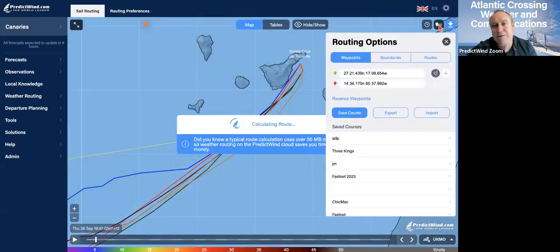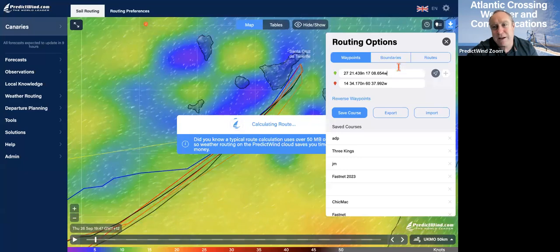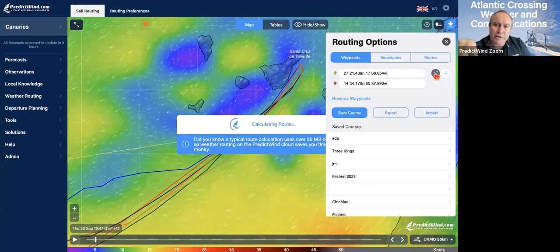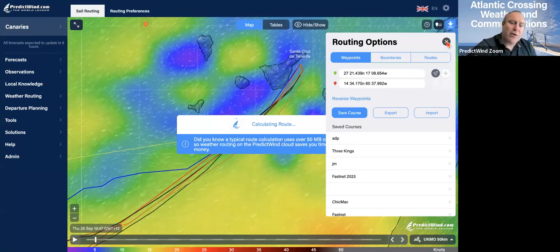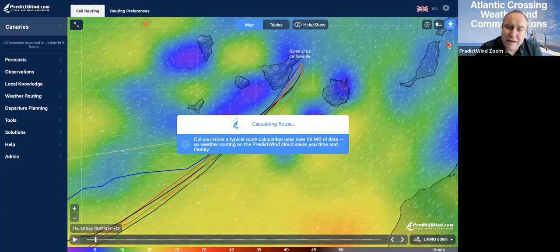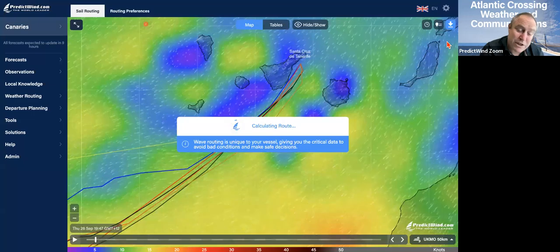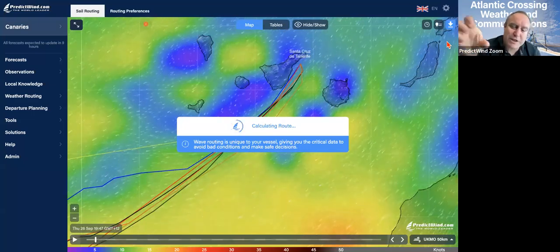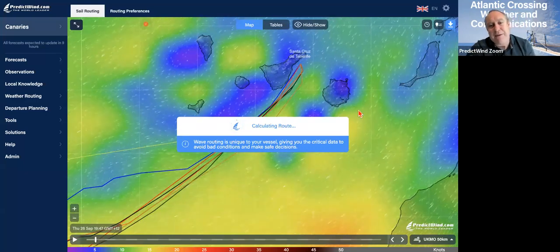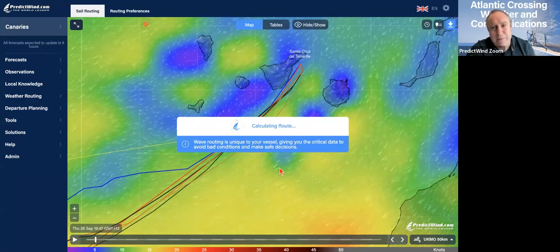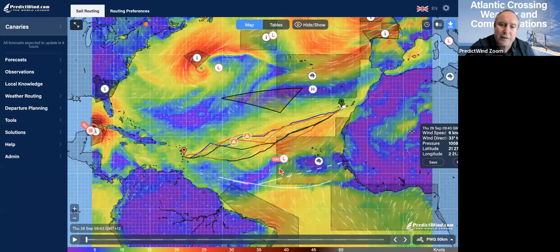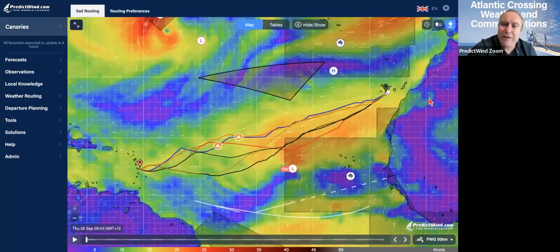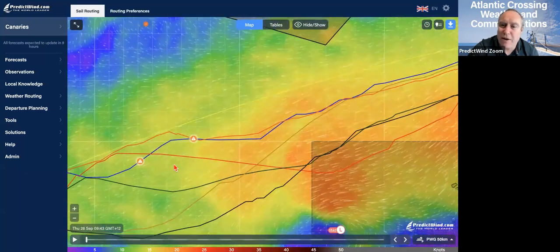So we would get to there and we rerun our route. And this is one of the reasons why you can enter the lat long in there, or the GPS position from there. Also the data hub and an Iridium Go, if you're using the offshore app, will transfer your position into there. We just need to put where we are now into the routing and rerun our route. And we will do this after each model update time.